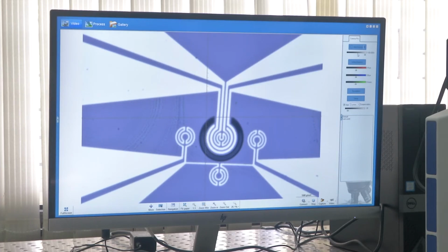So resistance temperature devices change their resistance as heat is impinged on them. That's the idea. So the idea is that you heat the micro heater to a particular temperature, you put a sample on top of the sensor, and through the micro heater that temperature will spread, right, and that change in spread through the sample will be detected by the RTDs. That is the general idea about the working of the sensor. And there are a lot of applications which we are not allowed to divulge. So this is how you make a sensor design.